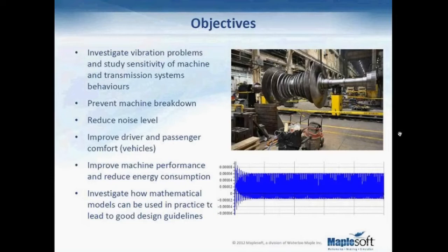We all know that all rotating machinery systems experience oscillation to some degree during startup, shutdown, and continuous operation. Consequently, the torsional response characteristics of rotating and reciprocating equipment should be analyzed and evaluated to ensure the system's reliability, because excessive vibrations can result in gear wear, gear tooth failures, or broken shafts. This is very important to prevent machine breakdown, reduce noise level, or improve operators' comfort level.